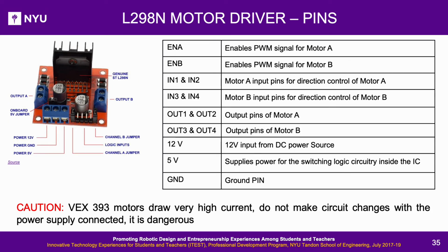L298N motor driver pins. The pin diagram for the L298N motor driver is shown on the left and tabulated on the right. Use this as a reference for interfacing the VEX 393 motors in the next activity. Caution. The VEX 393 motors draw very high current. Do not make circuit changes with the power supply connected.